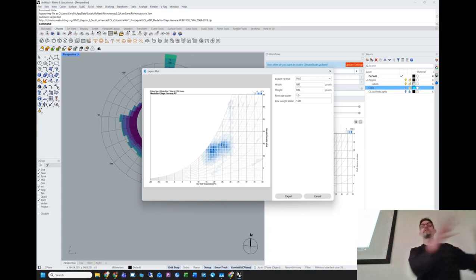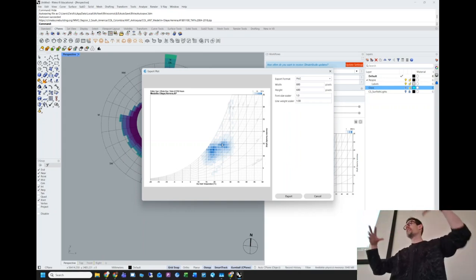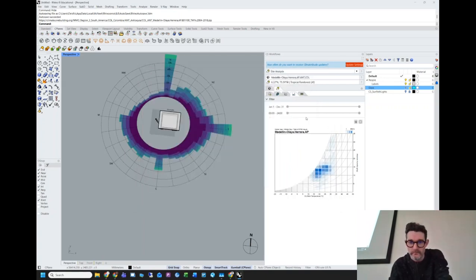So basically, we're on this curve. Generally what happens is the hotter the air is, the more moisture can hang around in the air, which is why there's this curve to it. This is really, really useful, especially if you're designing a building that uses something like active ventilation or stack effect ventilation, where evaporative cooling is an important part of it.